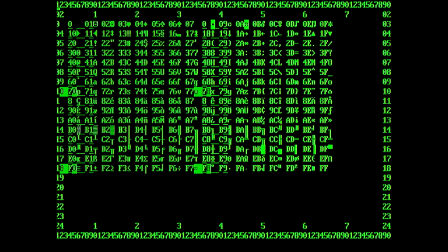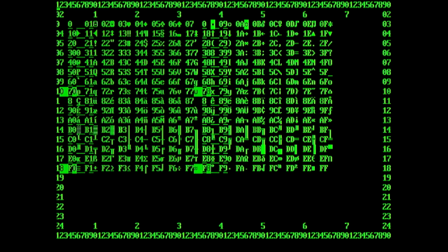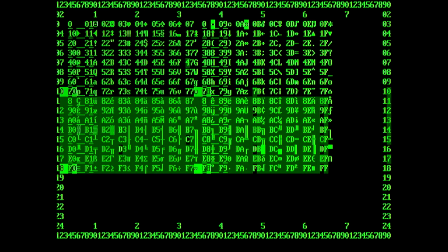And then I've got a further test program that disables the blinking. So I'll just load test 6, which just disables the blinking. And we can see here, because the blinking's been disabled, then when the attribute 7 bit is set, it actually gives us the higher intensity background that gives us a dark green. So you can see here that it's actually coming out a bit better. This looks a lot closer to what we were expecting.